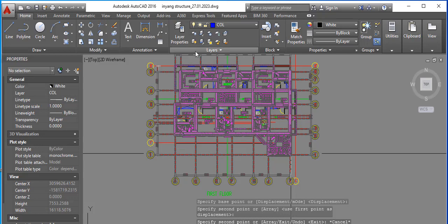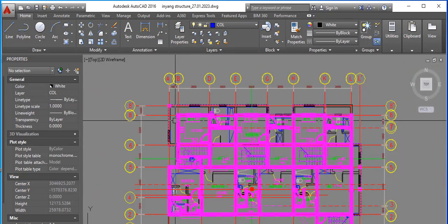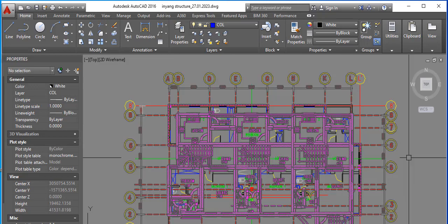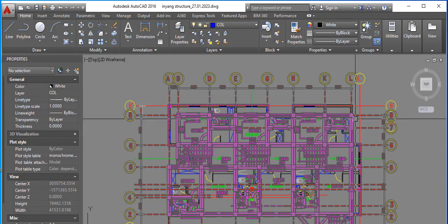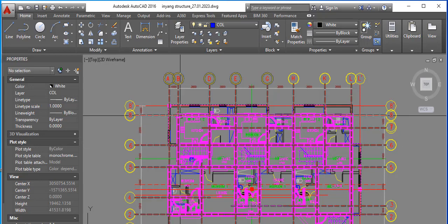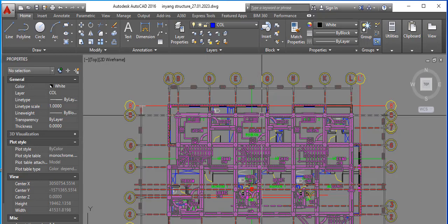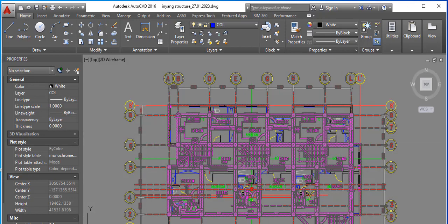So when you superimpose it here, what you can see is these are your ground floor where your beams would be. Then anything outside there will now be cantilevered. Pay attention, very important. This is your beam arrangement. Anything outside this ground floor area becomes a cantilever.